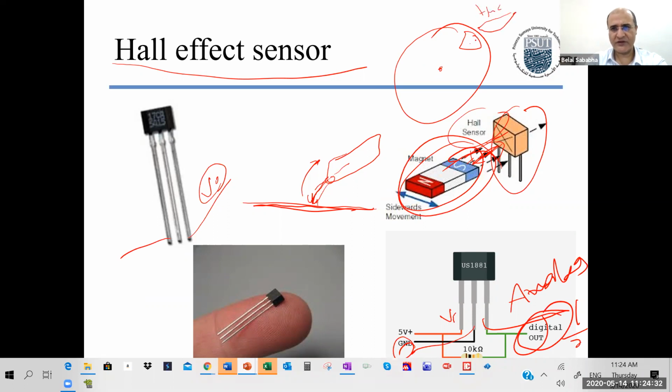If this is turning, and you get a digital signal, so you get a pulse, a 1 every time this magnet is close, then a pulse, right? So the number of pulses within a time period, these are the rotations per minute. If you put 2 magnets, a magnet here and a magnet here, then you will count double the time, but you'll have more resolution, half of the rotation. So many useful applications.